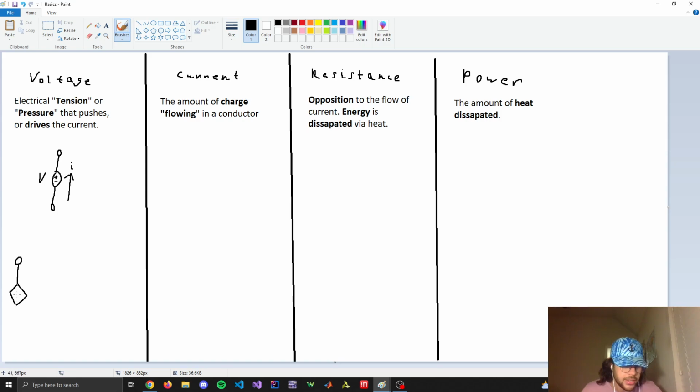There are two kinds. The first kind would be a voltage controlled voltage source, which means the voltage V is multiplied by another voltage Vx, which is a voltage drop somewhere else on the circuit. So this voltage drop somewhere else in the circuit will change this voltage V depending on the value of Vx. So that's a voltage controlled voltage source. V is a function of Vx.